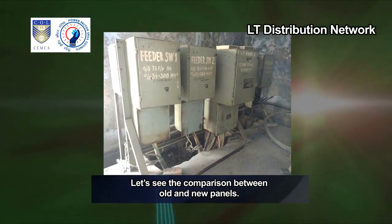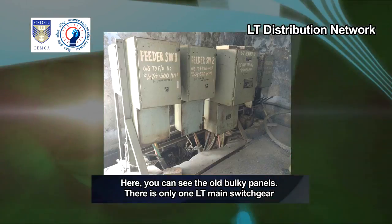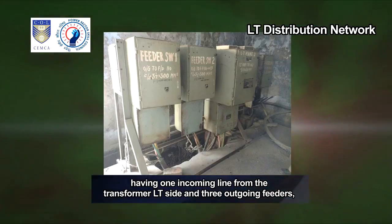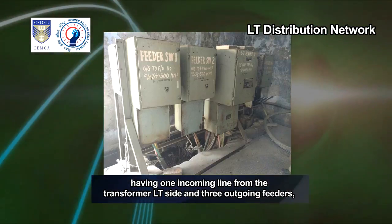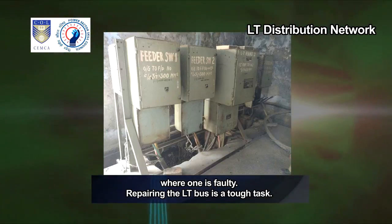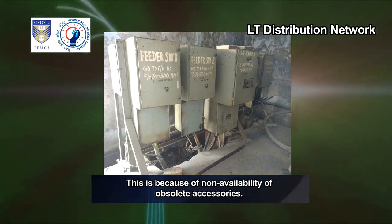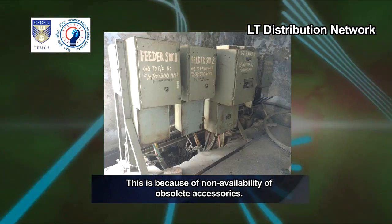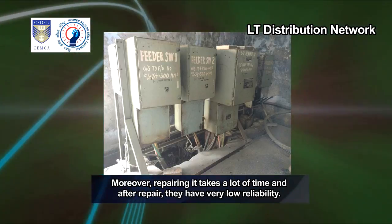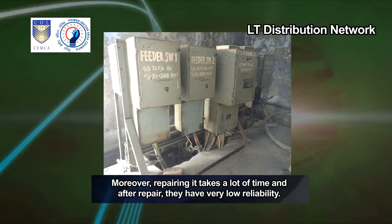Let's see the comparison between old and new panels. Here, you can see the old bulky panels. There is only one LT main switchgear having one incoming line from the transformer LT side and 3 outgoing feeders, where one is faulty. Repairing the LT bus is a tough task. This is because of non-availability of obsolete accessories. Moreover, repairing it takes a lot of time, and after repair, they have very low reliability.